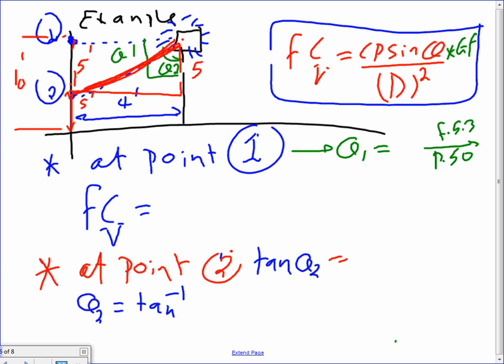So I have a fixture on a 10-foot high pole. It's shooting light on a wall. The wall opposite is going to be for the most part 10 feet, right? And the fixture is 4 feet away from the wall. Cool. Here's the 4 feet. And my question for you is, I would like you to do the calculation at point 1 right here, opposite. Can you see, straight opposite where the fixture is, at the same level? And I want you to do a calculation at point 2, which is basically 5 feet down, right in the middle of the center of that wall.